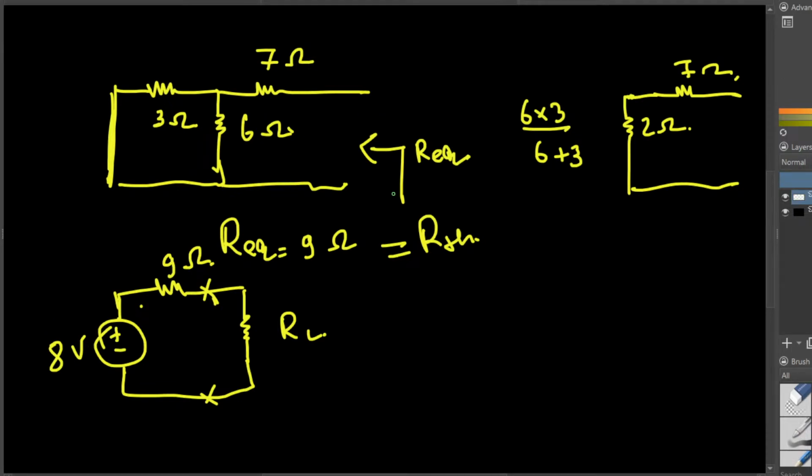calculations. Now, some people prefer Norton over Thevenin. So you can also convert this one into a Norton equivalent circuit as well. How do you convert? You have to do the source transformation.